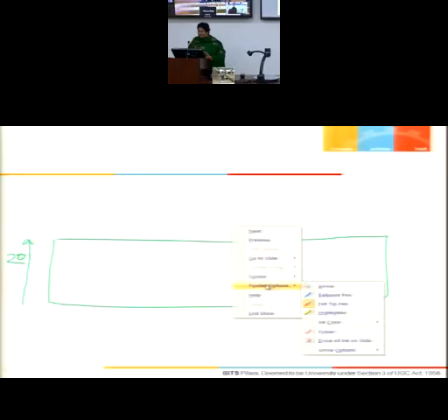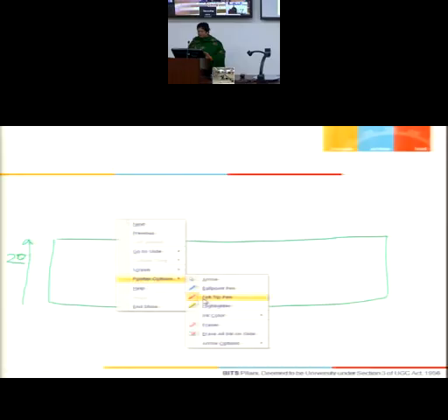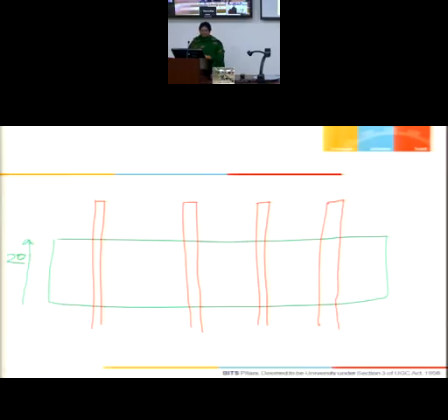Now there are going to be 5 gates. So I have 5 fingers. Let me choose red now. Red will be poly. So I will have the first gate. Now you have to expand it. Okay, or should I draw it like this? 1 finger. This is the second finger. This is the third finger here. Not a very good layout, but I think I am able to give you the idea. And this is the fourth finger. Make it like this, 4 fingers. That is why the name is given as multi-fingered gate layout.